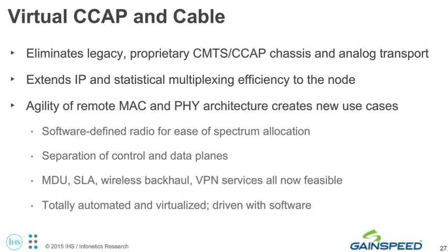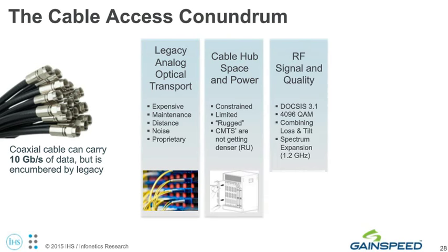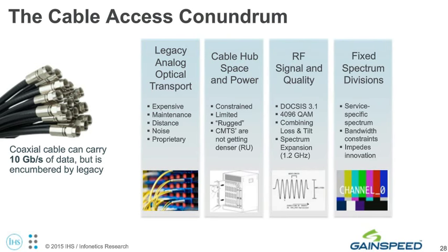But before we get into that, one of the big things that we see today, and Andy alluded to on the access side, is bandwidth is very incremental in terms of 6 megahertz channels; you have a certain amount of DOCSIS capacity. But when people look at bandwidth to the home, the coax really isn't the problem. There's a lot of conversations around, should we go fiber to the home? What's the evolution of the last mile? But that coax connection going into everybody's house is fundamentally capable of doing 10 gigs. It's really encumbered by the way it's been used today, right?